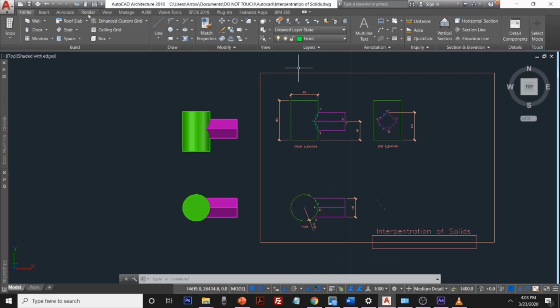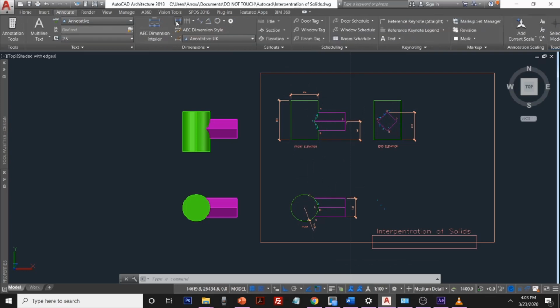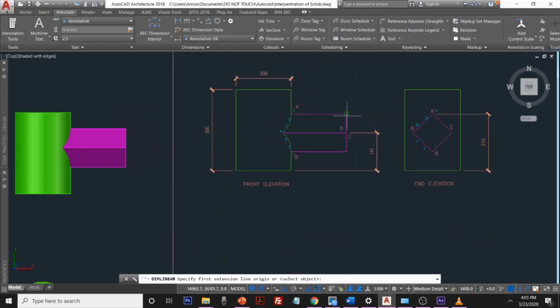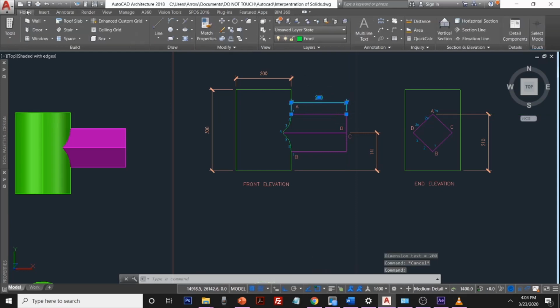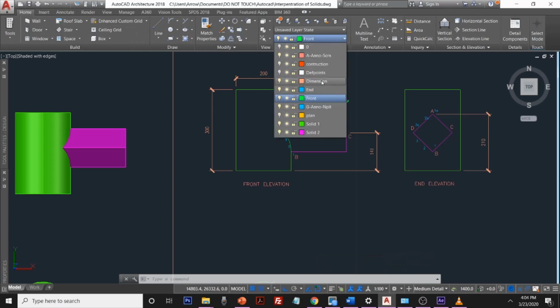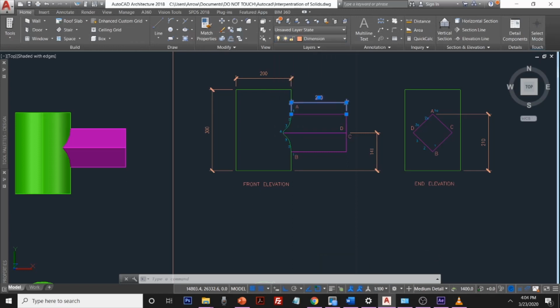That part I did not add, to show you how that is done. For example, the distance from the end of the cuboid to the first part of the intersection can now be placed in the drawing, and that should also be placed on the correct layer, so it should be showing peach, not green, and there you go.